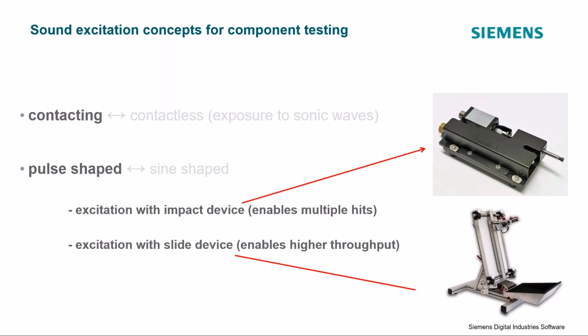It can also help you to avoid false rejects, because if, let's say, the gripper places the part in a tilted way on the part settlement, well, the part settlement is narrow for the sake of reproducibility. At the same time, it shall not clamp the part because this hinders it from vibrating.